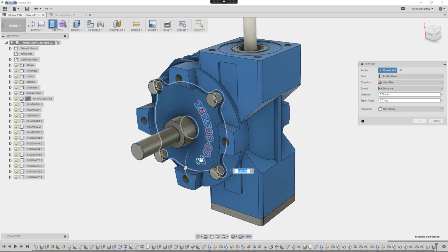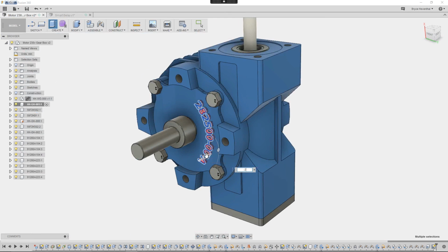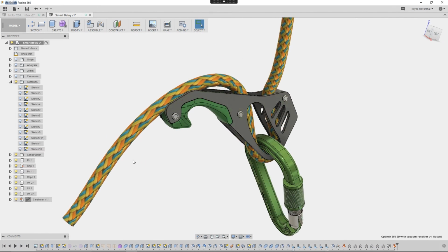With all of these sketch entities selected, I can turn this into an extrude. But first, I'll deselect a few sketch regions that I do not include in this cut extrude. This will ensure that we can box select sketch entities while in a sketch without having to play the hide-show game when bodies and other sketches are visible.